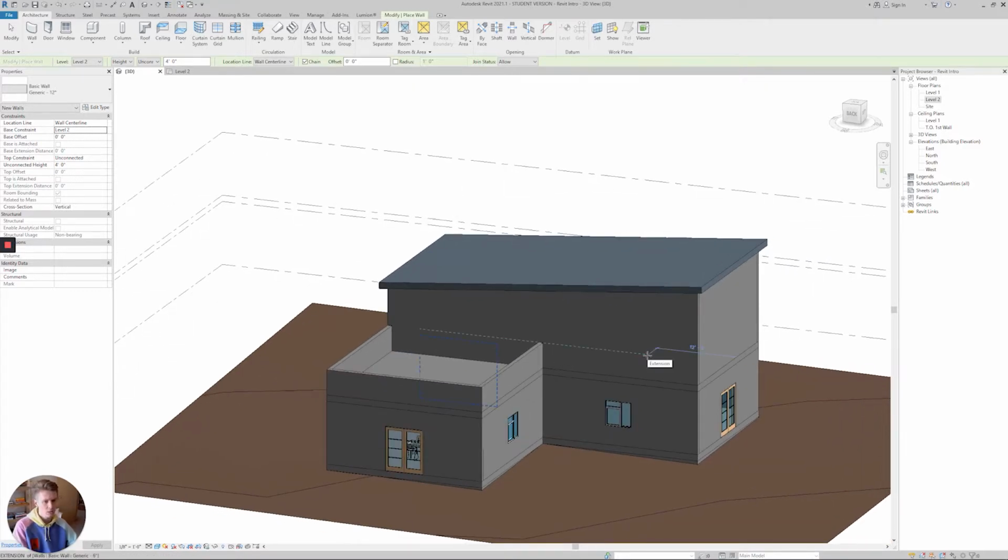So curtain walls, the name kind of implies, and if you're in your structures class you'll have learned this, they're not structural walls, they're hung from the structure, so the wall in this case. And so you shouldn't be using them on their own to frame a building, you should rather be embedding them into walls so that your building can still support itself.